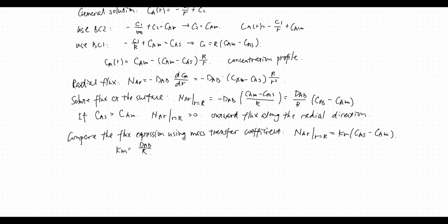Does the example we covered in the lecture cover your scenario? If yes, you can use the equation corresponding to that example. If not, then you cannot use the Km we derived here. This Km is a very nice looking simple form, for this particular problem, which is a spherical surface diffusing into an infinite stagnant medium.